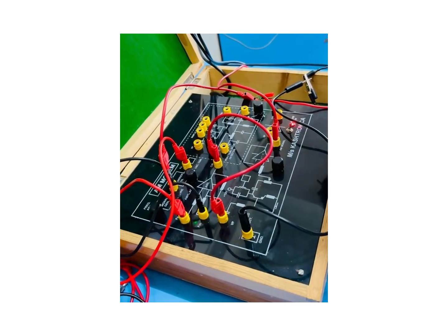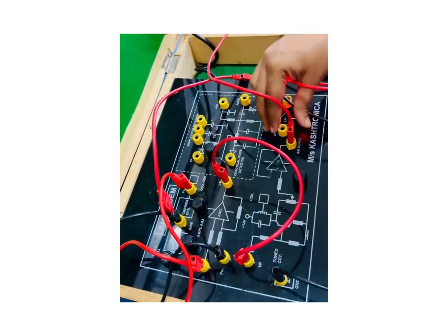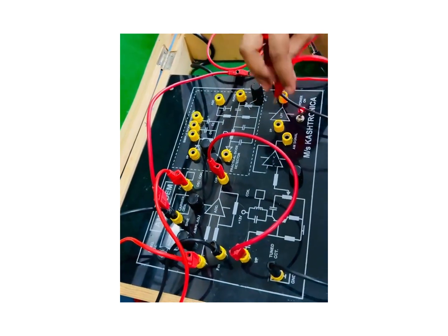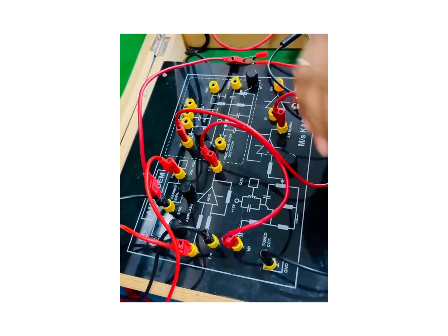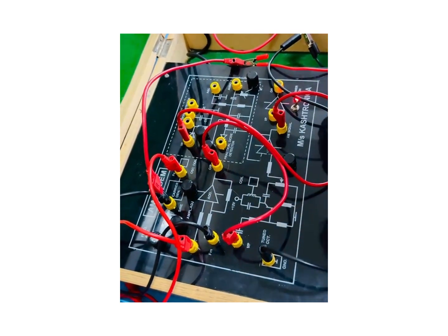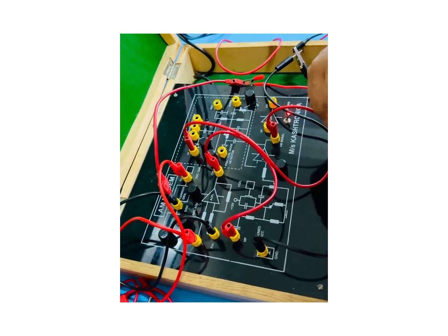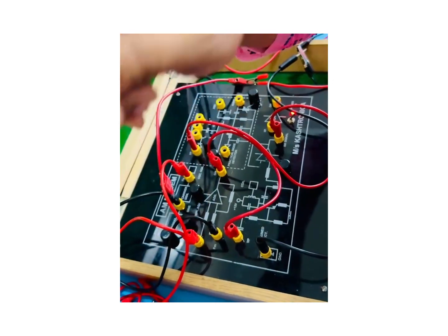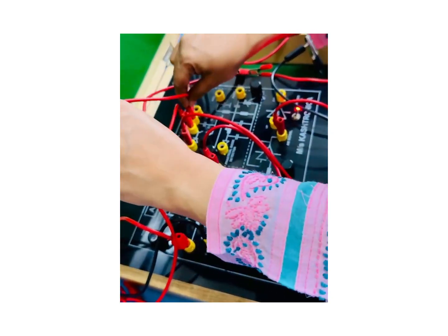pattern. For demodulation using a simple diode detector circuit, the AM signal is to be connected to the input of the diode in the diode detector circuit, and a capacitor is to be connected in the circuit, which will charge and discharge to the positive going pulses in the AM signal.